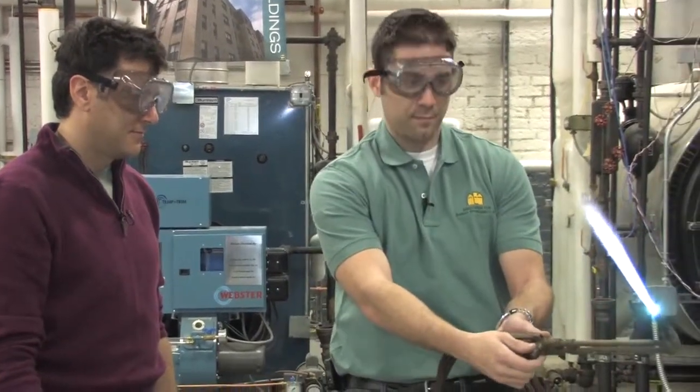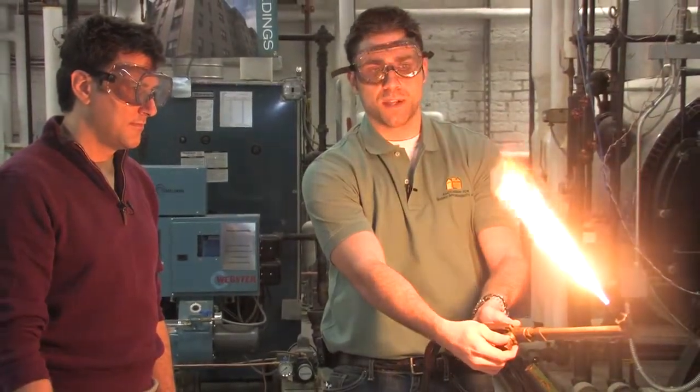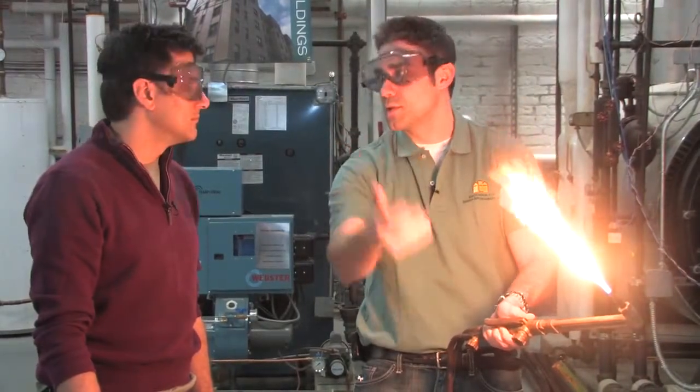Shut her down. And as we go back and we take the oxygen away, we start to get that dirty fuel again, that burning combustion. It's incomplete combustion. So you get a lot of carbon monoxide being produced as well inside here.